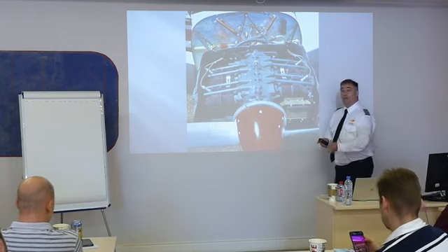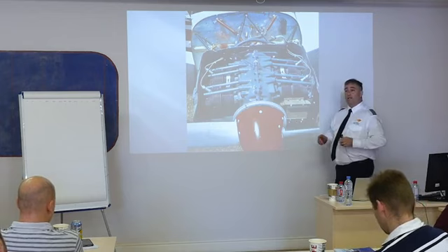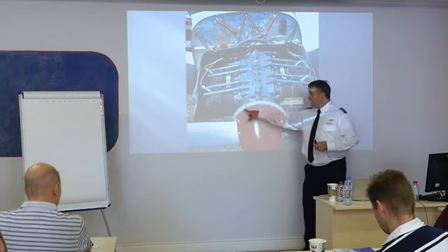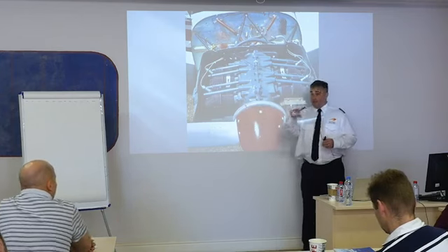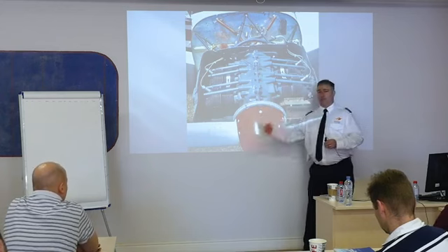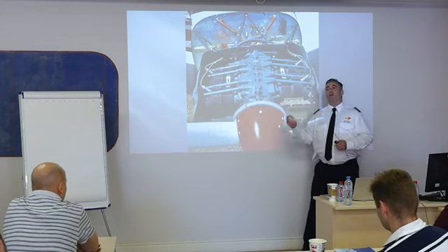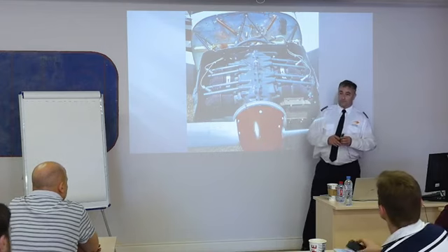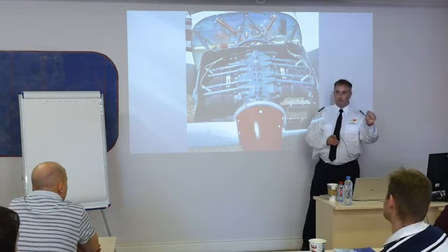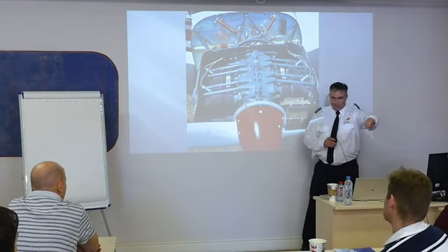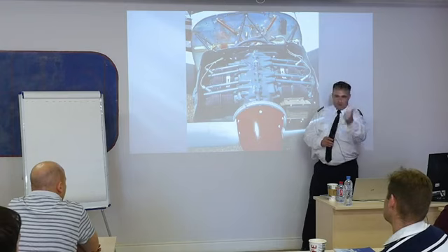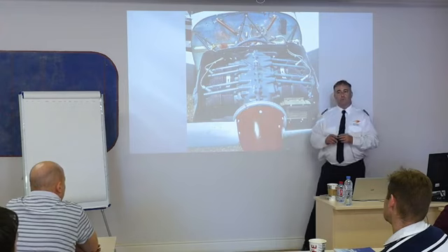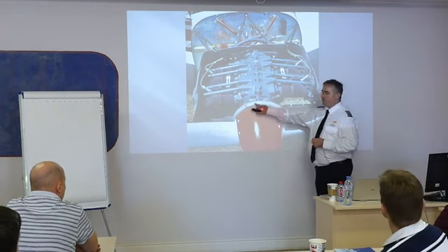Instead, we'll turn a key, and that key will close the circuit for the starter. The starter will momentarily engage the flywheel and spin rapidly so that the engine can start. What's very important is that immediately after the engine starts, you have to release the starter. You don't want to continue to hold that starter because a couple things happen. It's breaking the starter, and it will slow the engine down so it won't run. Okay? So this is part of the starting mechanism.